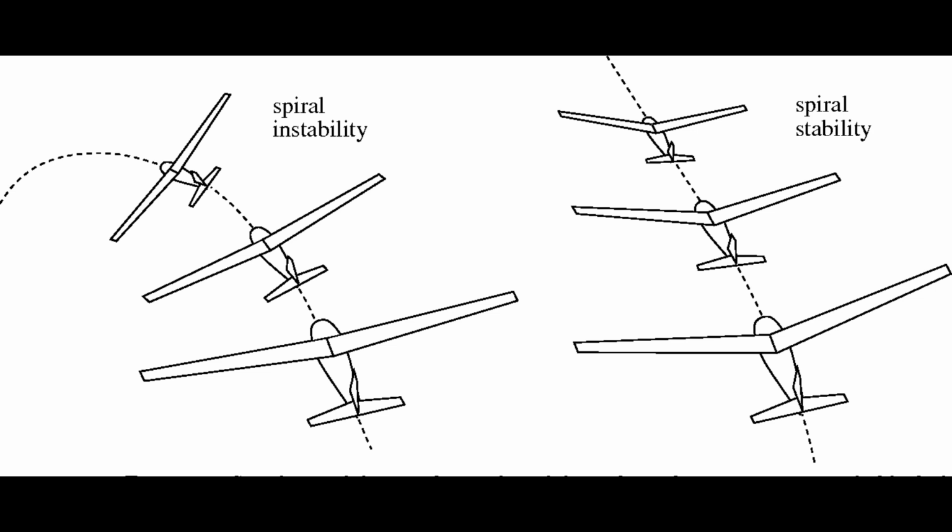Due to this yaw, the wing on the outside of the turning moment travels forward faster than the inside wing and, as a consequence, its lift becomes greater. This produces an overbanking tendency which, if not corrected by the pilot, results in the bank angle becoming steeper and steeper. At the same time, the strong directional stability that yaws the aircraft into the relative wind is actually forcing the nose to a lower pitch attitude. A slow downward spiral begins which, if not counteracted by the pilot, gradually increases into a steep spiral dive.